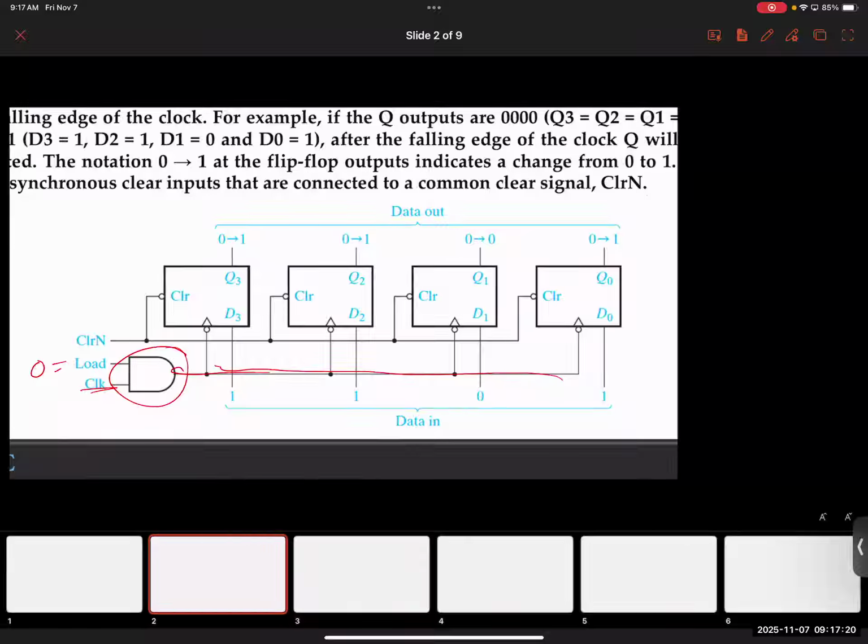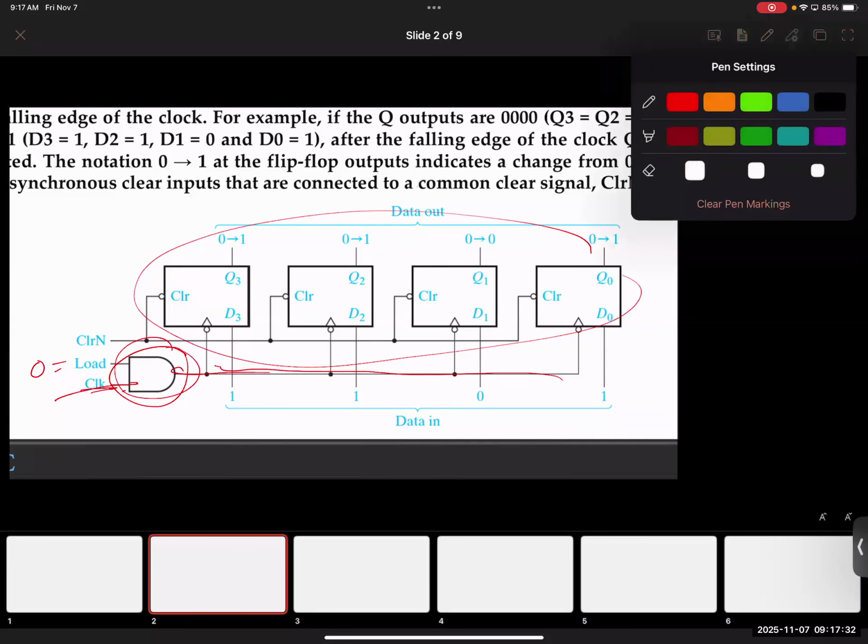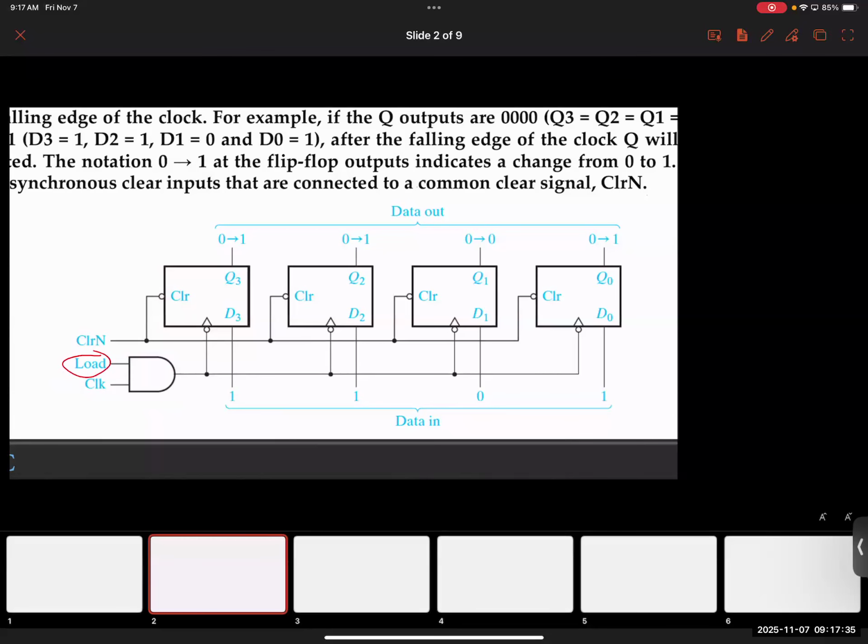Without killing it for the entire chip. This is a simple, easy-to-explain example. For this particular register, take the clock input, but don't provide it directly. Use an additional gate and merge it with an additional control signal. Now, this control signal will essentially control the practical clock that this register gets. Does that make sense, folks?